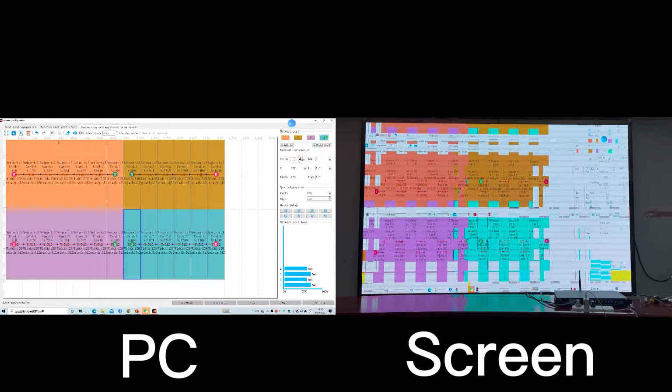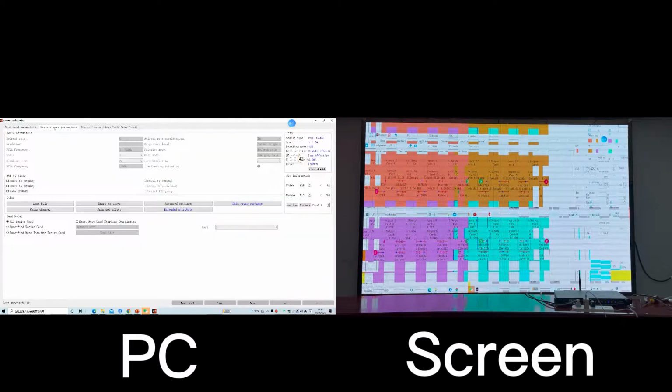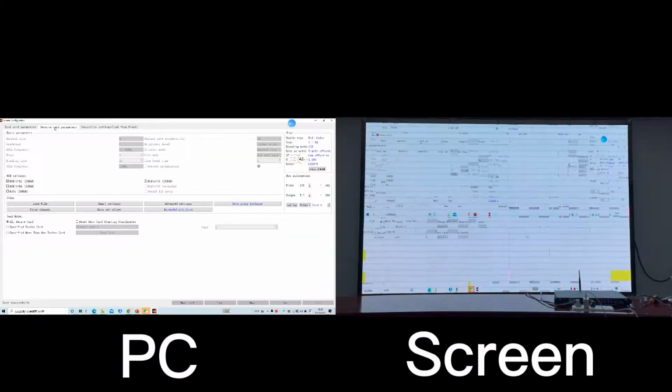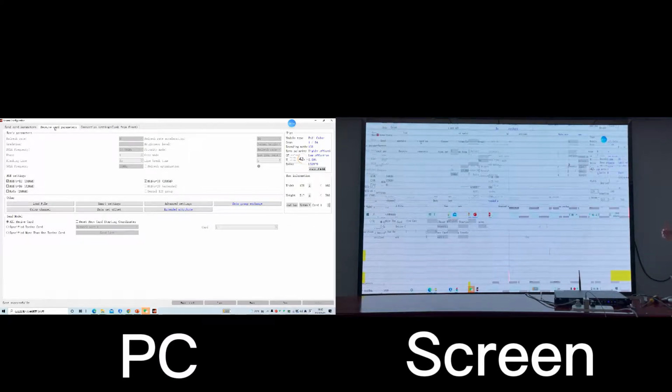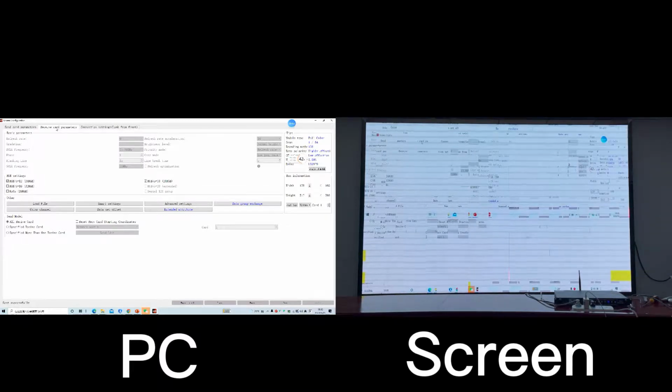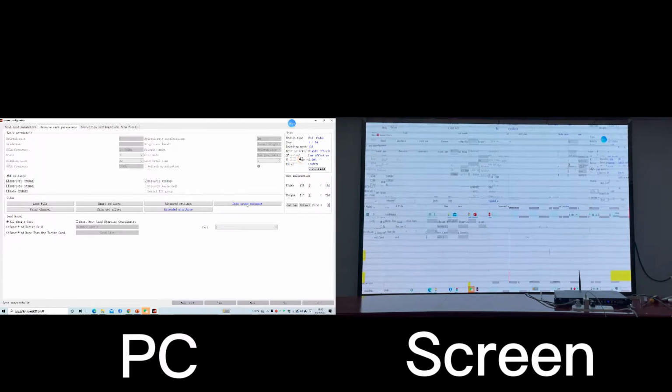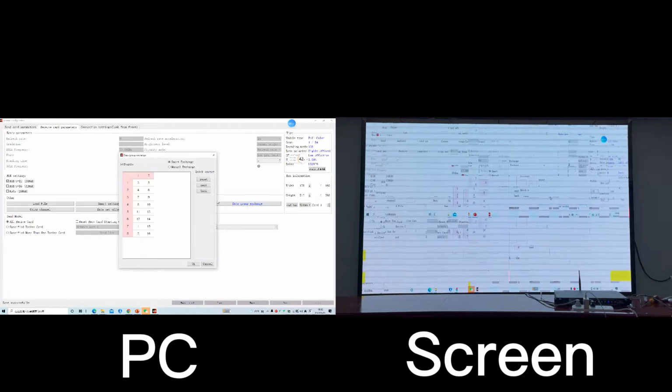But after finishing the connection setting, the LED wall still does not display correctly, because there is some offset of data, since this module has a two open output set design. So the data group is not normal, and we need to figure out the right data group setting.